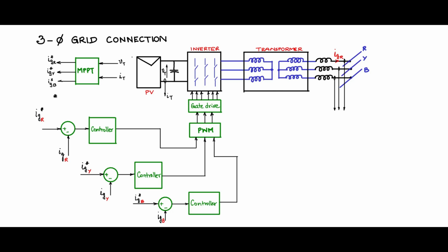From that you take the unit sin omega t term, and the MPPT outputs will give what is supposed to be the Im value, the peak value, and Im sin omega t, Im sin(omega t minus 120), and Im sin(omega t minus 240) degrees, you will be setting these references, and these references will come in here. You will measure all these three currents, and then based on that the control action will happen and current control will take place.